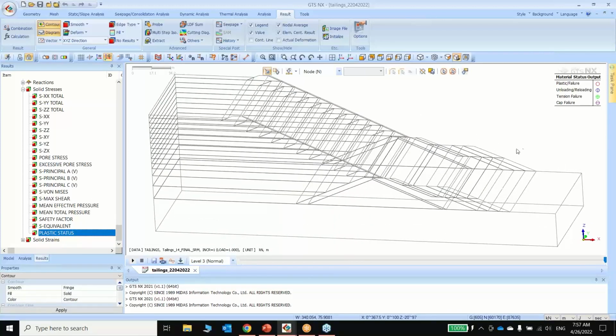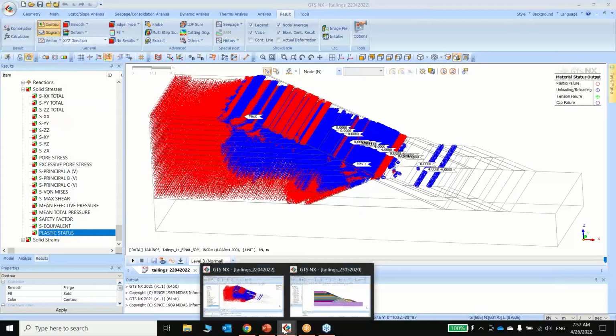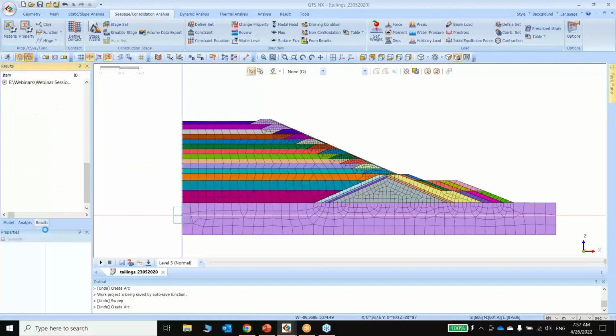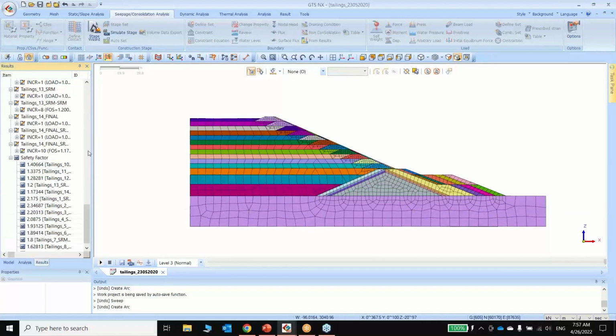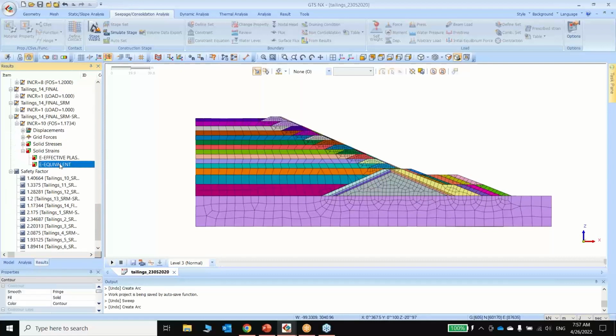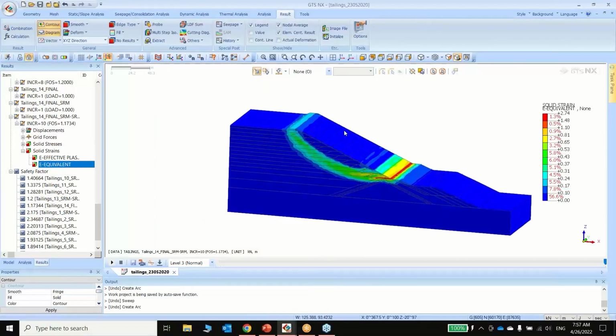So finally, we come to the factor of safety results. Actually, I created two models for this. I ran them side by side, because again SRM is an iteration method, so it takes some time to get the results. For factor of safety, like we saw in the chart, you can see the variation of factor of safety. For the final raising, this is how the slip surface looks.